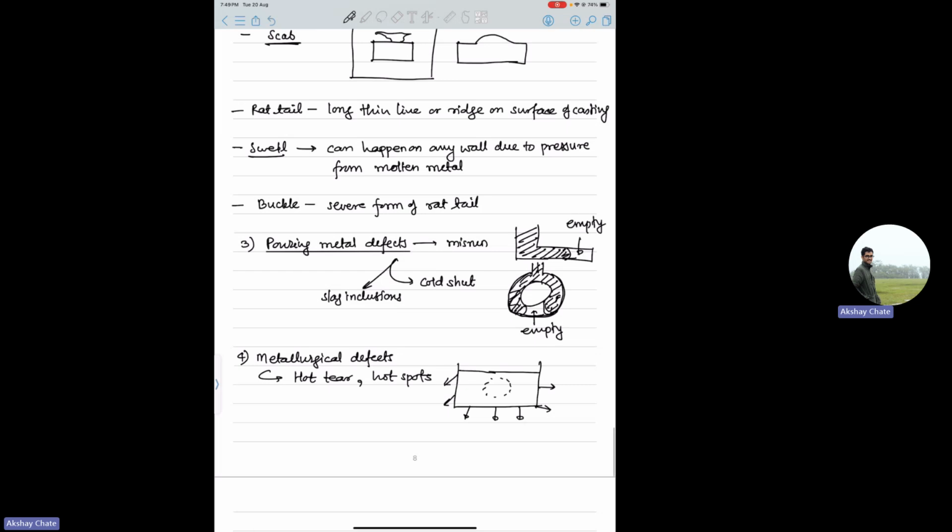And therefore, at the top of this material, assuming that this is also closed, sometimes something like this forms because it gets pulled, because when it solidifies, the volume reduces, right? So this part becomes empty because of the pull from the solidified part, or the heat transfer being more in that direction. So instead of having a full casting, you have hot tears.